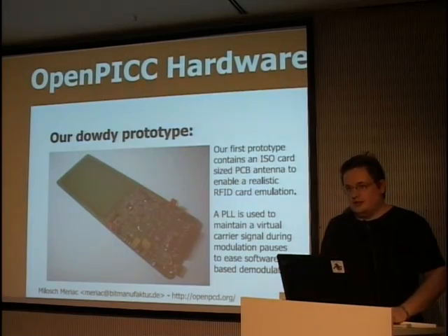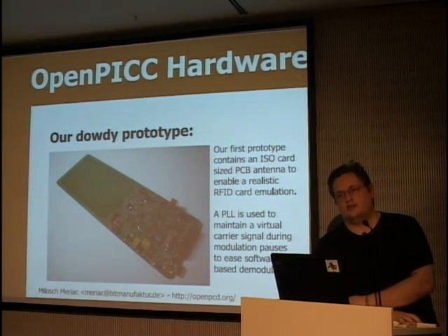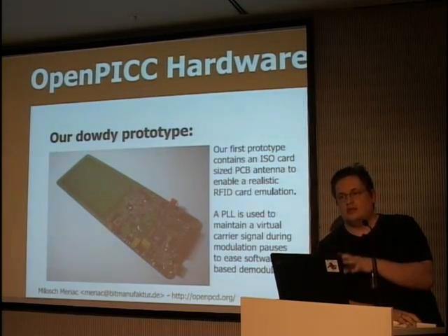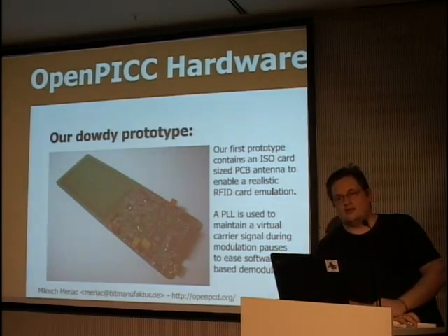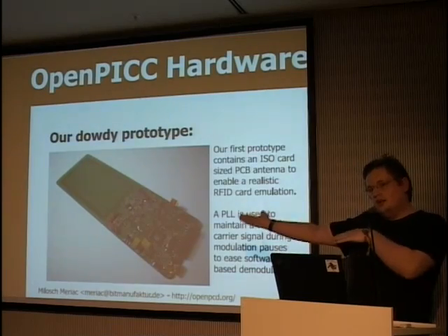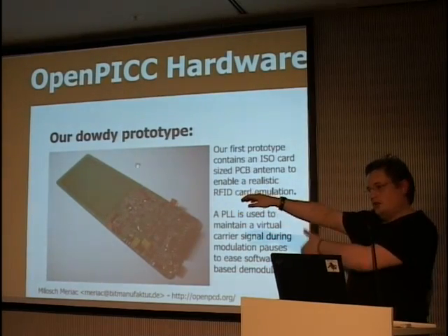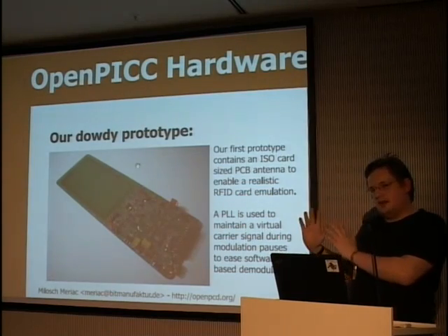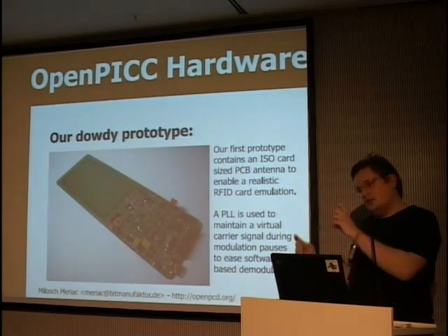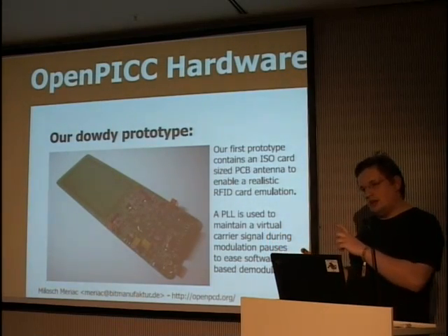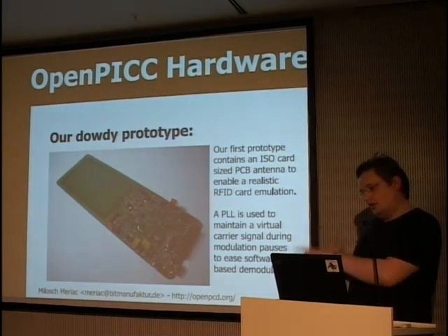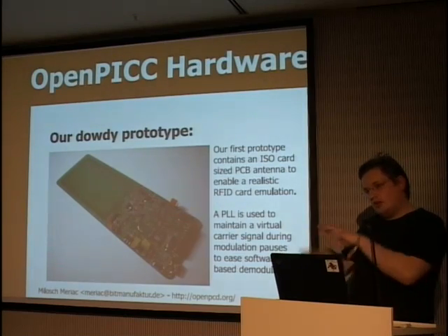There is also another topic. There were also two possibilities to solve this topic, in software and in hardware. But as I indicated, we want to make it as simple as possible. So, for example, if you look at modulation and demodulation patterns, they are naturally all aligned on a timeline, and you have a clock or whatever where these are relatively aligned too. But in this particular case, as I indicated, we use the reader field to generate this 13.56 megahertz digital signal, which is derived by our timer signals to our internal clocks.